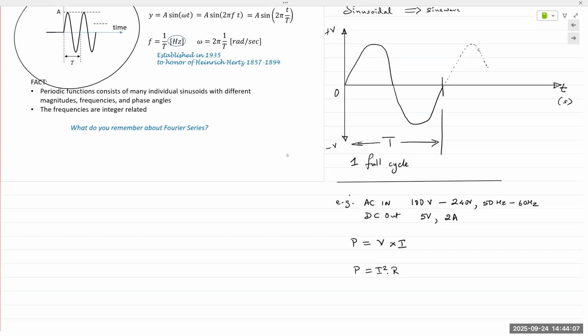Long distance transmission lines that you have seen running all across the country are hundreds of miles long. And so when you're traveling hundreds of miles, there is some resistance. A lot of power is dissipated as heat. There are energy losses that occur. So if you increase the current, the power loss increases as the square of the current. So you want to keep the current low and increase the voltage to transmit the same amount of power.